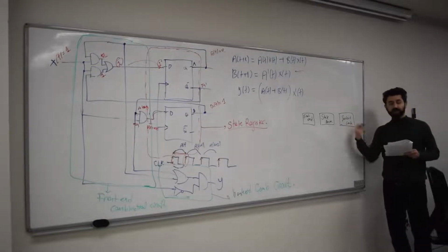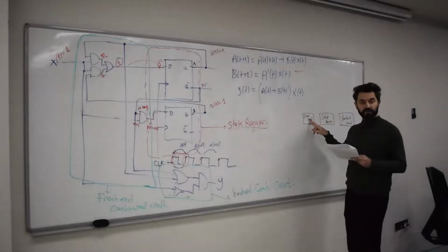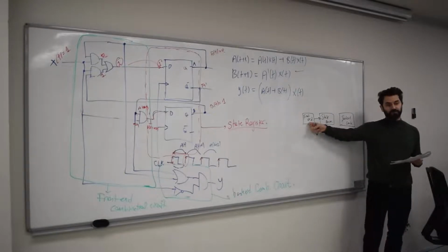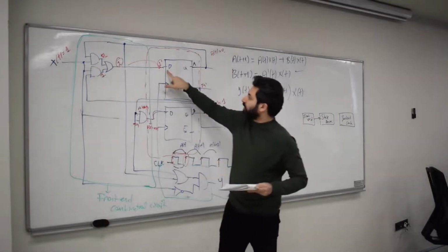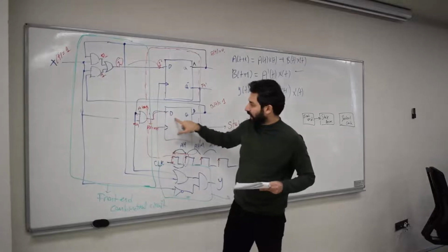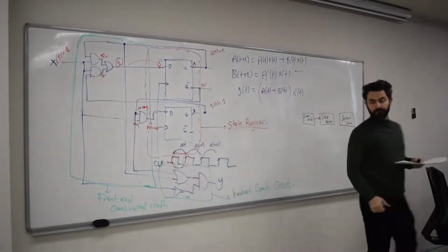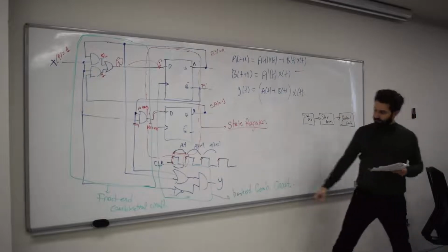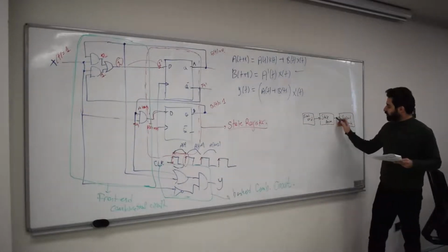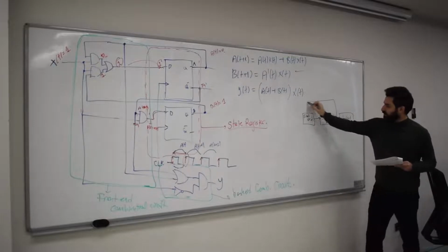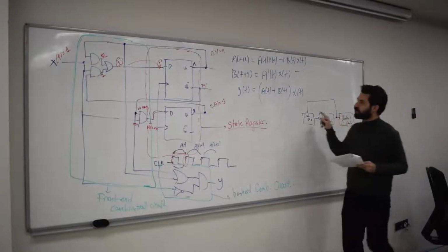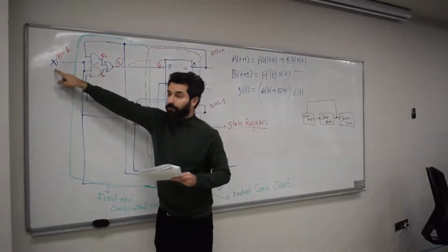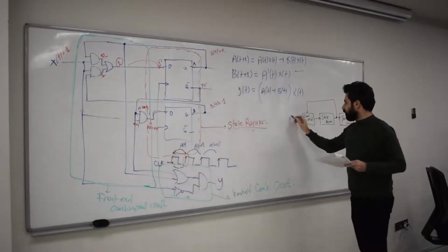So the relationship between these blocks: you use the front end to provide the state information. In other words, inputs of these flip-flops come from the front end. As you can see, it's the case here. This input becomes your next state, and this input becomes your next state, and these come from the front-end combinational circuit. And of course, state registers generate an output for the backend. And state registers can be used by the front end to generate the next state. These outputs are fed back into the front-end combinational circuit, along with the input, to generate the next state.